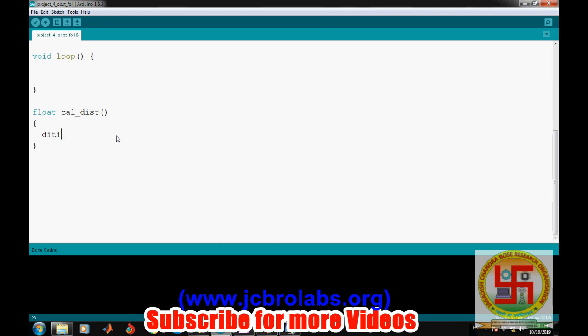So for that, first we will write digital write trig comma high, right, and then we will create a microsecond delay of 10 microseconds, and then we will make it low. Digital write trig comma low. So as soon as a low pulse goes there, it sends an ultrasonic burst, right, and now we should calculate the duration of the pulse.